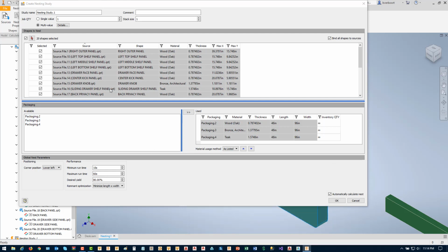These values act as multipliers for the component quantity in the nest. In addition, we can adjust the stack size, which would enable us to stack multiple sheets of material on the machine to be machined together for increased efficiencies, obviously decreasing runtime and also helping get high tolerance match sets of components cut at the same time.